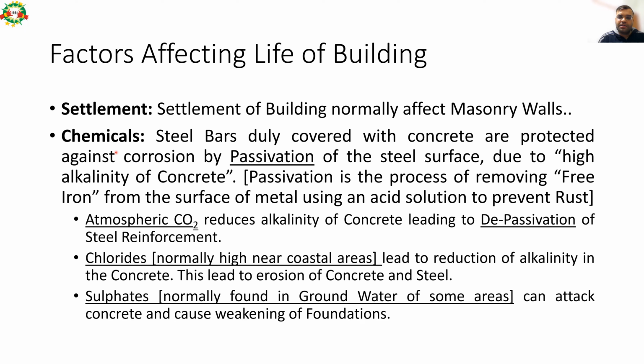Then chemicals. Steel bars newly covered with concrete are protected against corrosion by passivation. So this is a keyword, passivation, a theory question can come. Steel bars duly covered with concrete are protected against corrosion by passivation of steel surface due to high alkalinity of concrete.